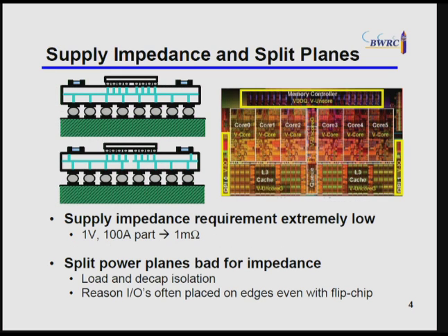But even if you ignore that issue, there's a very big practical issue, which is that if you think about especially the very high performance space, at the very high end, these parts are typically operating at about 100 watts or so. Now, you should keep in mind that 100 watts is actually done at 1 volt, which implies that you need 100 amps of current flowing into the part. So if you run the quick back-of-the-envelope calculation as to what impedance you need through that entire power distribution network in order to ensure, for example, just a 10% voltage drop, in other words, 100 millivolts, that basically means you need something on the order of a single milliohm of resistance in that entire distribution network, okay?